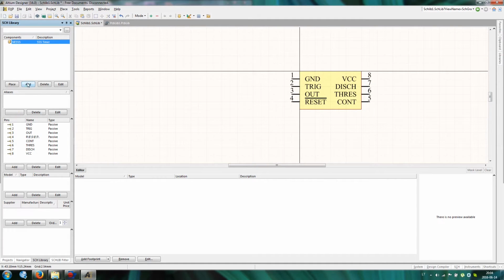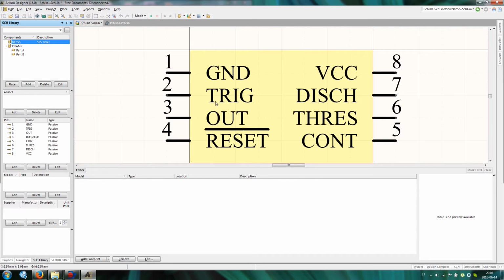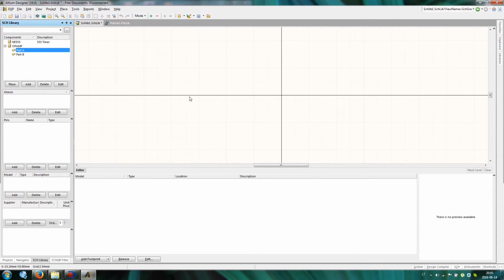There's another trick. That's like op amp. If we have op amp, like it's created from 2 parts, there is op amp A and op amp B inside one package. We can make tools, new parts. So basically, it will create 2 parts, and we just need to match same idea. Create component. Just we don't need to double pins. Like if ground, you just make it on one part. You don't need to use ground for the second part. But you should have power supply defined in some of these parts.